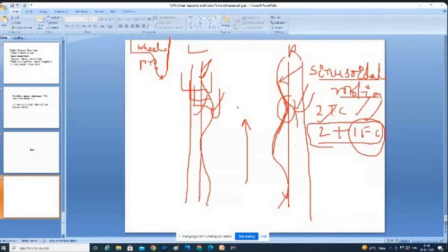Whenever only 2 thread contacts are there, that implies that left side also gap is there, right side also gap is there. If there is no gap, that implies there is one more additional contact, that is called 1 flange contact. So that is why here you have to understand very neatly what are the forces that are caused whenever additional flange contact is there, what will happen to the rail and wheel. That was studied by one famous railway engineer.